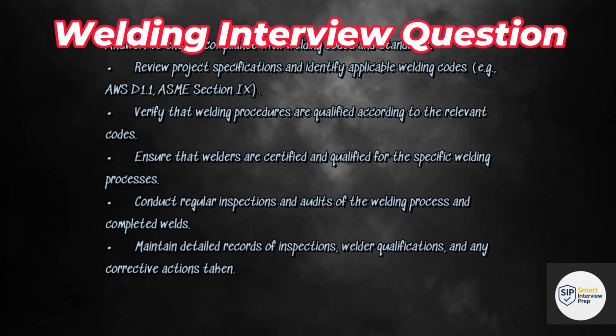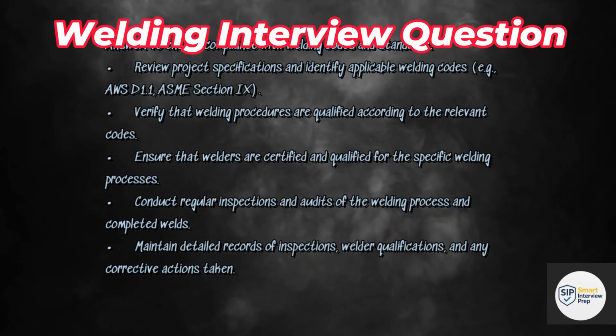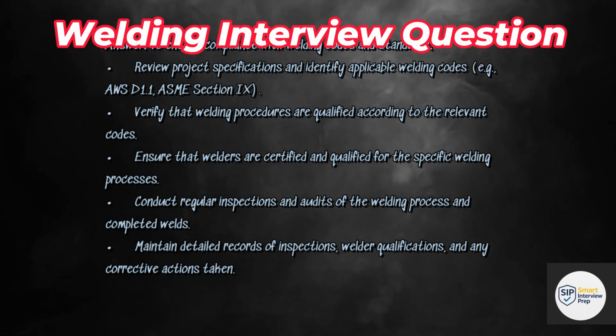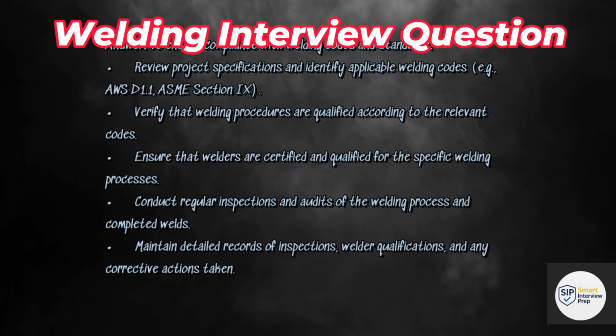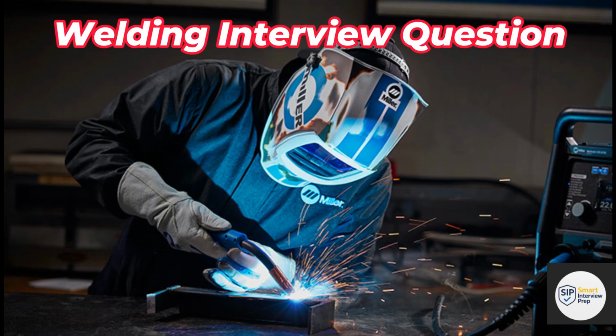Ensure that welders are certified and qualified for the specific welding processes. Conduct regular inspections and audits of the welding process and completed welds. Maintain detailed records of inspections, welder qualifications, and any corrective actions taken. Communicate with the project team to address any deviations or nonconformities promptly.